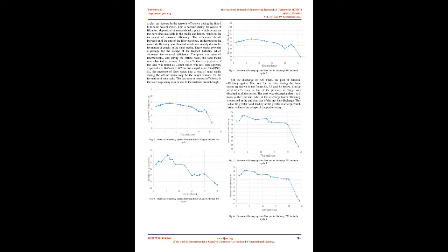is undergoing backwashing. The interval between successive backwashing depends on the quantity of floc not settled down in the sedimentation tank. The water for backwashing is pumped from the clear water reservoir. For this purpose a vertical pump of 7.5 HP capacity is used. The underdrainage system consists of manifold and laterals of HDPE pipe.